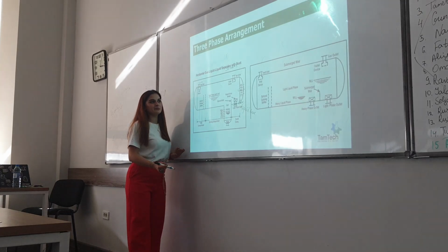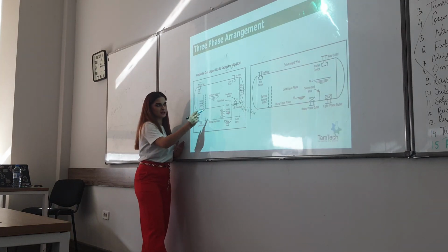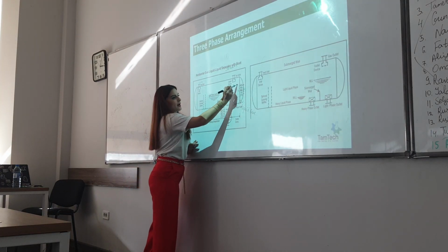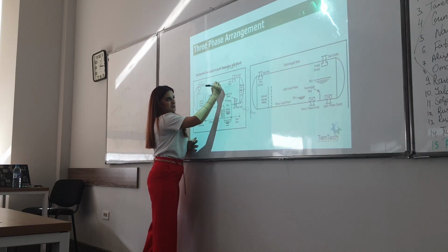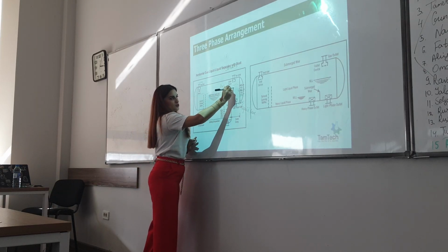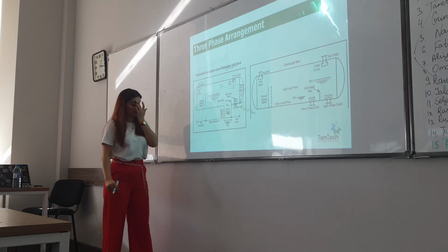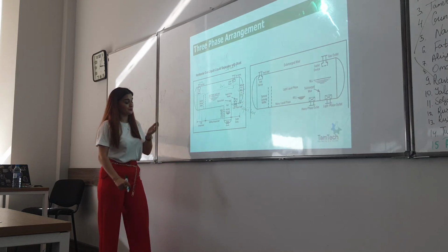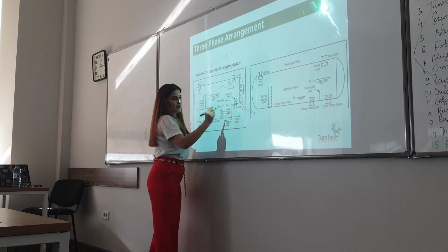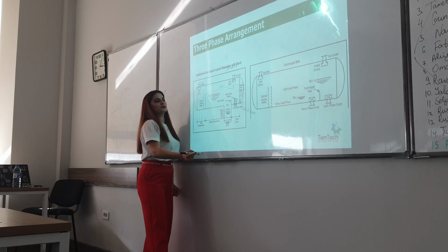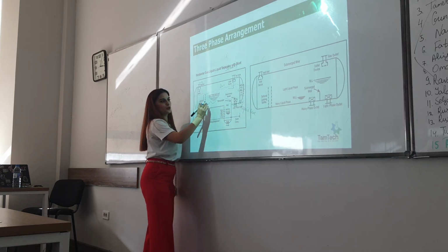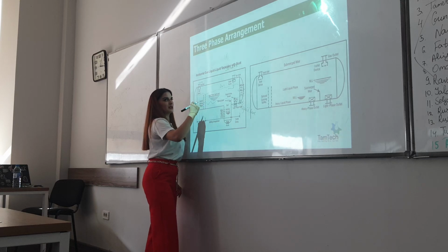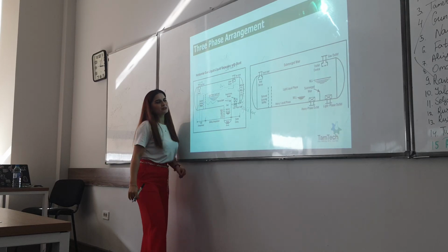For example, if I say this is an overfill scenario, it means we have already reached the high level, and this is the gas part, right? The liquid is entering the gas, and it affects our separation. This is the high, this is the low. But in the low case, just imagine you don't have the necessary amount of liquid.